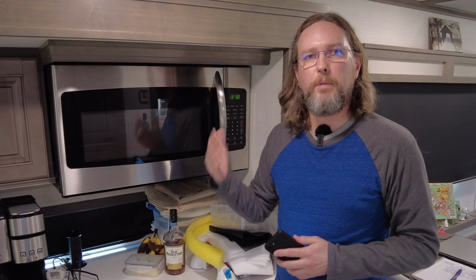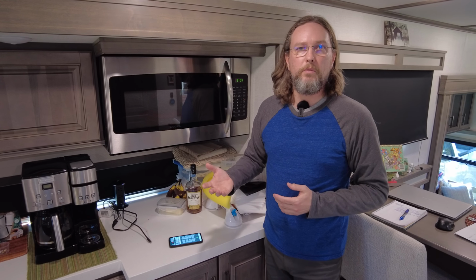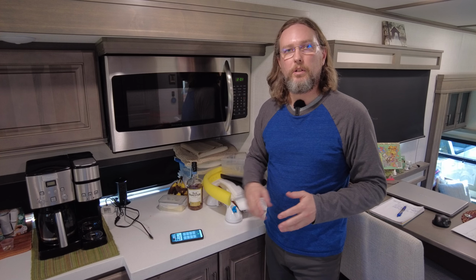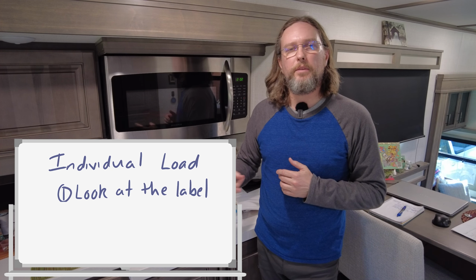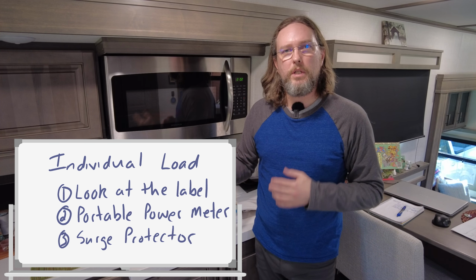And I didn't really need to use this app on the microwave because it plugs in right inside of this cabinet here. But what I would use this app for is maybe on the air conditioner, where it doesn't plug into a 120 volt outlet. So the only way to really monitor that power usage from an air conditioner is via this app, at least for me. Those are the 3 different methods I would use when you're talking about the individual load technique during a power audit.